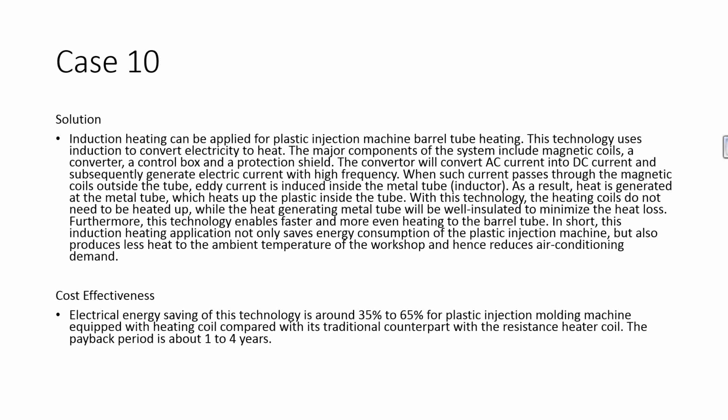The cost effectiveness for this will be electrical energy saving of this technology is around 35 to 65% for plastic injection molding machine equipped with the induction heating coil compared with the traditional counterpart with the resistance heater coil.